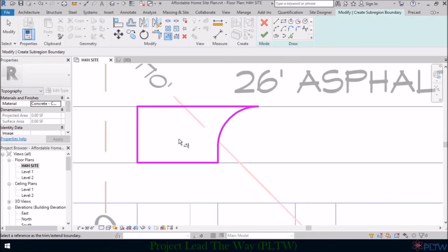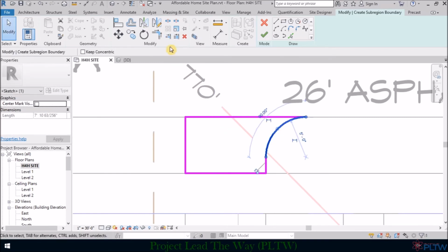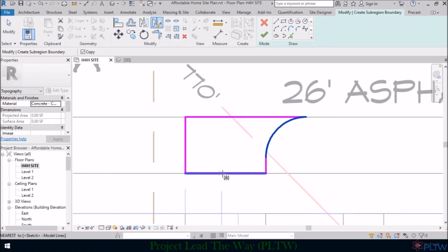So you can repeat the same steps on the left side, or you can take a shortcut, which I'm getting ready to do myself. So I'm going to choose this arc. I'm going to choose the mirror draw axis option, and I'm going to choose this midpoint of this part of the driveway, and I'm just going to go straight up until it is perpendicular or hits this edge of the road, and it draws my radius right over here.